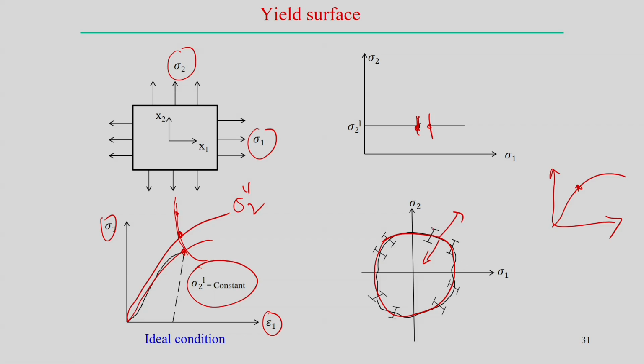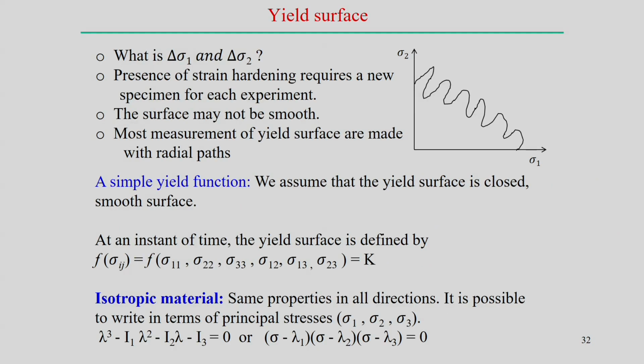So, that way, if we are not fitting an exact curve, there is some variation that happens during this process, but we roughly estimate this can be the closed curve on a stress axis that represents the yield curve when it is subjected to a 2-dimensional state of stress. Similarly, if it is 3-dimensional, then we define it as a surface.